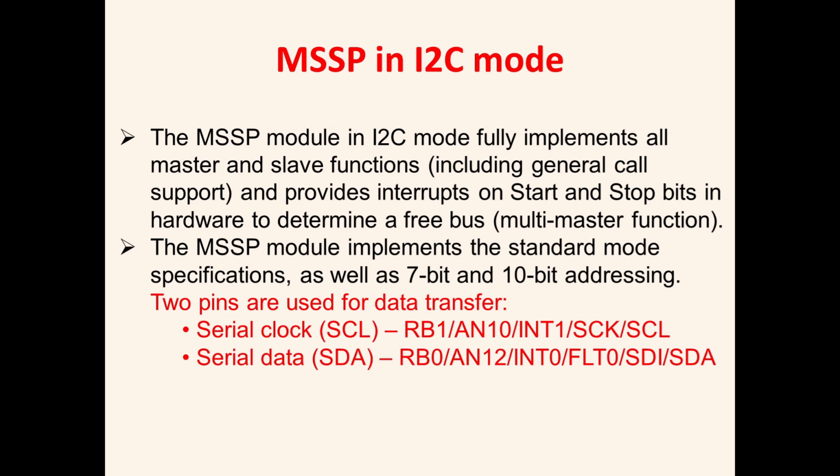For this purpose, there are some options available in I2C mode for the slave addresses. Either you can generate a 7-bit address or a 10-bit address is allowed. If a 7-bit address is there, 2 to the power 7 means 128 addresses it will be able to generate.